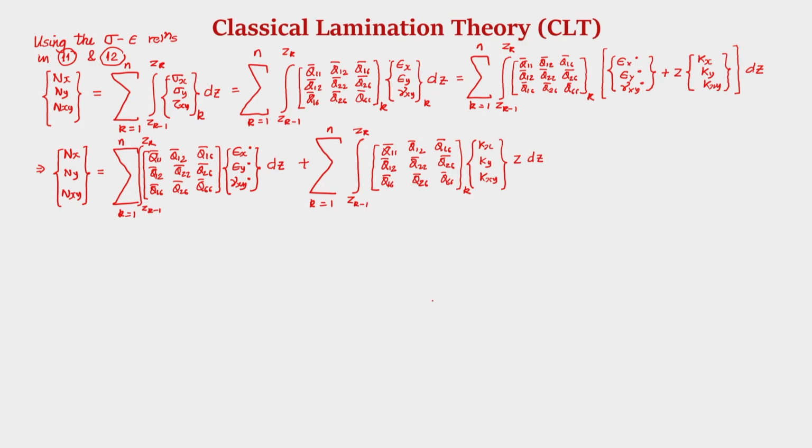So, now you could see that we could express the in plane force resultants Nx, Ny and Nxy in terms of the mid surface strains and the curvature. Of course, along with that, the properties of that layer, that means the reduced transformed stiffness of that layer, are there.